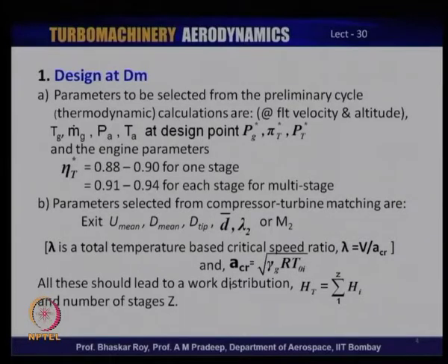We have seen that the number of stages in LPT often is more than that of the number of stages in HPT. That is because each stage of LPT is actually doing far less work than any stage of HPT, and hence typically the aggregate amount of work done in LPT could be of the same order as the aggregate work done in HPT, but the number of stages of LPT would be more than the number of stages in HPT. So, these are some of the standard features of axial flow turbine.